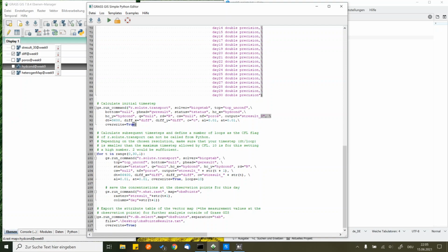Then I'm quickly doing one small time step. You see here, it's just very, very small to have an initial diffusion. Note again here that you need to provide a water source term, which is null, due to a bug, a mistake in the solute transport module. Physically, this is not necessary, but it is needed because of a mistake.